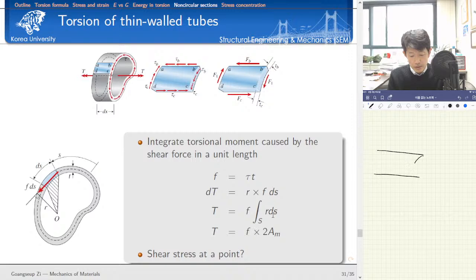As I told you, because the problem is homologous, the situation here is the same as the situation here, which means the shear stress that we measure at this point is the same as the shear stress measured at this point. Because of this logic, if we have some shear stress tau b, we must have the same shear stress tau b here. And then we can measure another shear stress at these 2 points. By the same logic, we have tau c and tau c. Make sure that this problem is homologous.